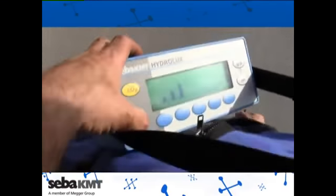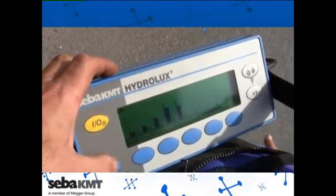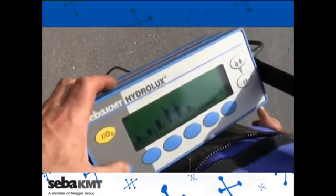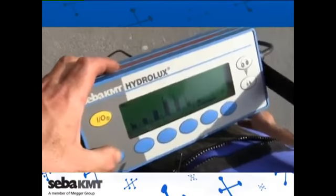Here the minimum recorded level value is displayed, with which the influence of the short-term interfering noises is eliminated. The additional option of filter adjustment further improves the suppression of ambient noise. Pinpointing with the listening device confirmed that the leak location surveyed by the PC correlator, labeled here with a point, was positioned exactly in the middle of the zone with an audible leak noise and thus confirmed as the middle of the excavation.